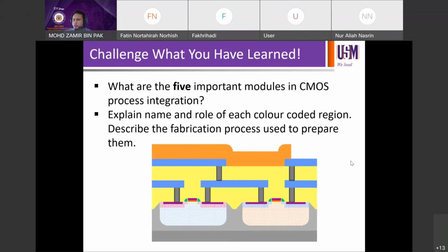In fact, if we talk about just transistors alone, there are already a lot of differences. If we talk about CMOS migrating to FinFET, FinFET migrating to GAA FET, gate-all-around FET, and the fin is what you're supposed to present, you can see the difference in the layers, in the configuration, in the details already. So not talking about other devices yet. If you go for other devices, of course, you should expect a different process flow, but with the same basics.